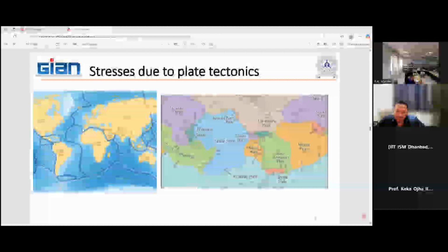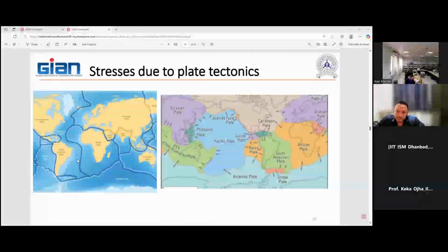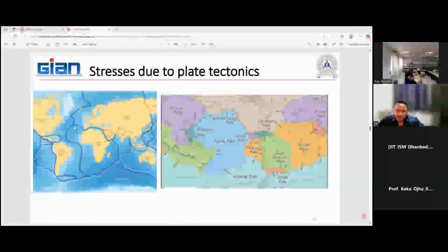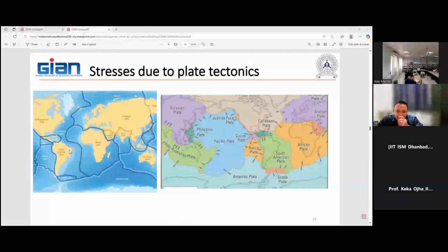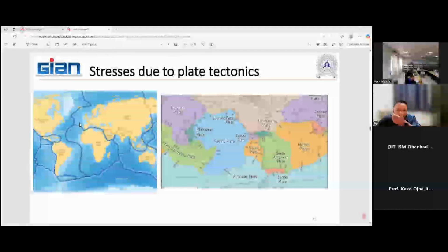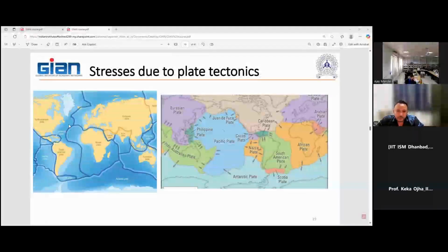And then you have places on the mid-Atlantic ridge where the plates are pulling apart from each other, and there is a lot of volcanic activity in these areas. New crust is forming. Europe and North America are moving about 1 inch away from each other every year. So because of these phenomena, your horizontal stresses are never equal. They will always be unequal, mostly.